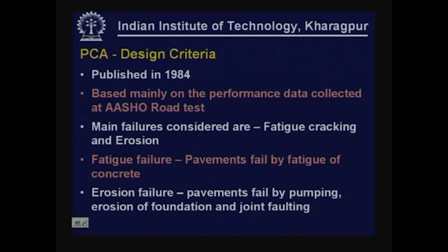Fatigue failure is the one in which the pavements fail by fatigue of concrete. Erosion failure is the one in which the pavements fail by pumping. We had discussed pumping in the previous lesson. Erosion of foundation leads to formation of gaps below the slab, and joint faulting, the joints being at different levels.